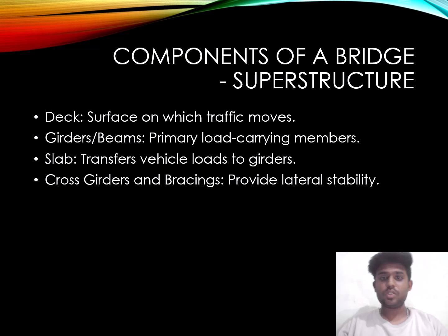Next, components of a bridge. First, there is the superstructure. Deck, a surface on which traffic moves. Girders or beams, primary load carrying members. Next, slab, transfers vehicle loads to girders, and cross girders and bracings provide lateral stability.